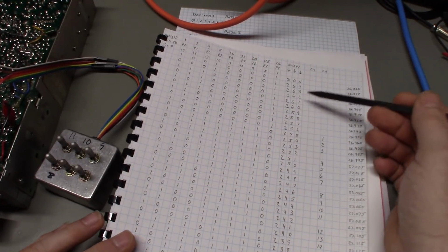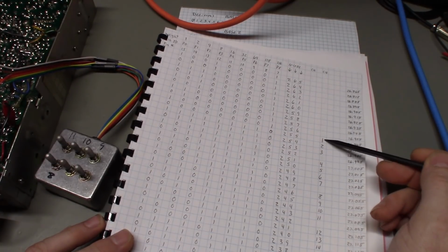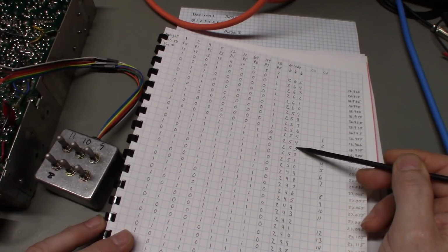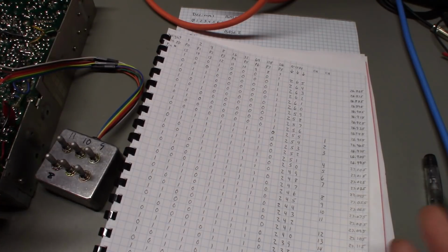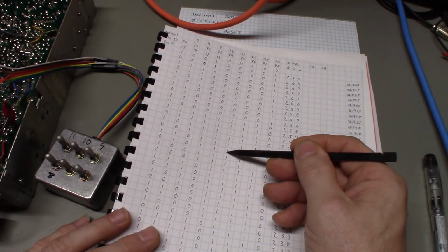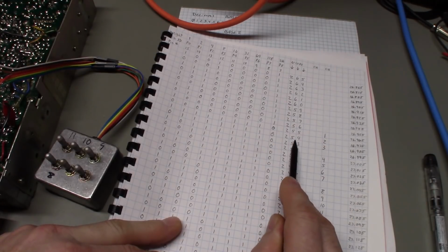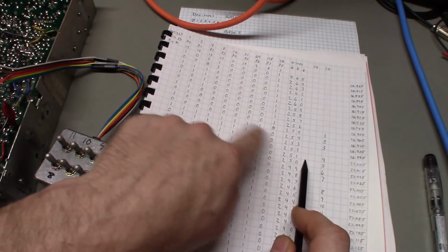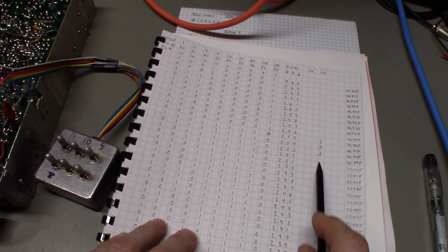If we wanted to go down in channel, look what happens. The encode increases. But what happens when you go from channel 1 to channel 2? The encode decreases. So this is another one of those cases where things are backwards. Don't ask me why. The people that made the PLL02A, that's just the way they made it. But when you're actually increasing in channel, the encode and the binary are decreasing. Because you can see 1 is 255, 2 is 254, 3 is 253. So as this number gets bigger, this number and this number, because remember, these are both the same thing, just different forms, base 10, base 2, these are decreasing while this goes up.